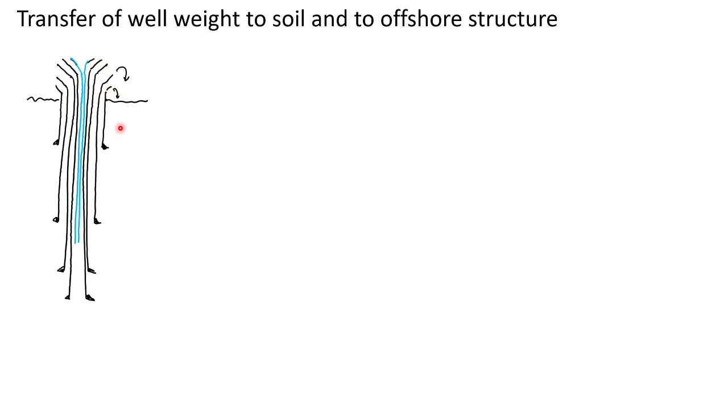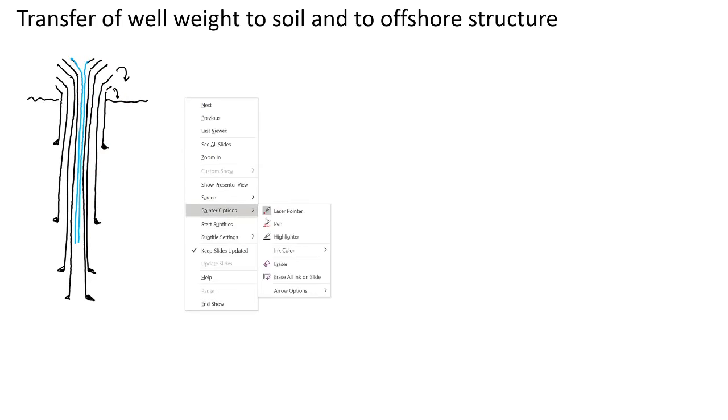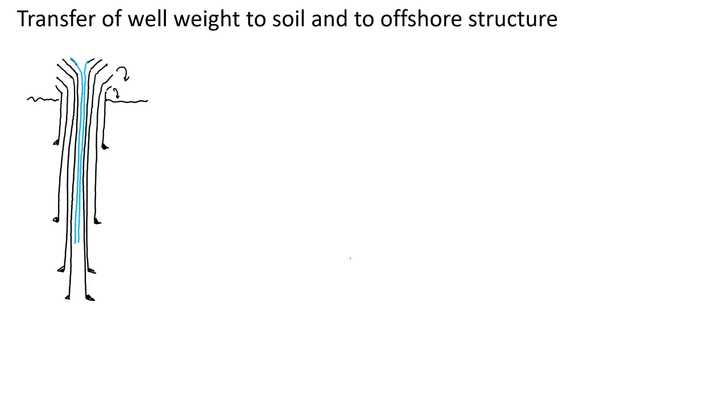And of course we need to have some seals in between. In this case you have a high inner pressure, and you don't want it to be transferred to the outer strings, because the conductor and the other casings are not that thick, so they don't tolerate the full reservoir pressure.